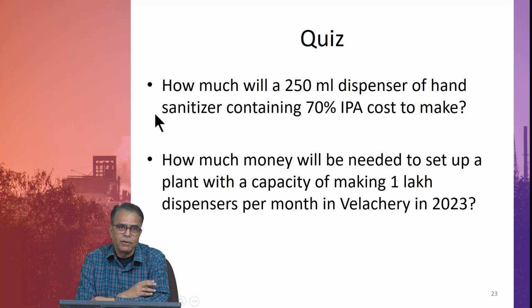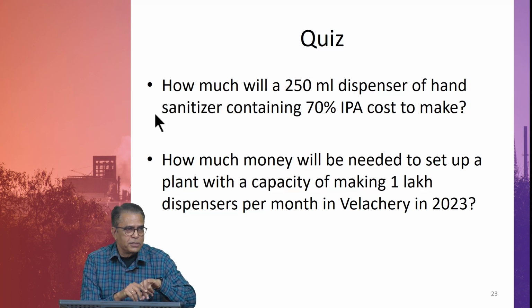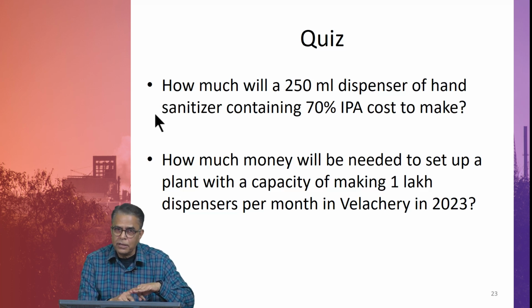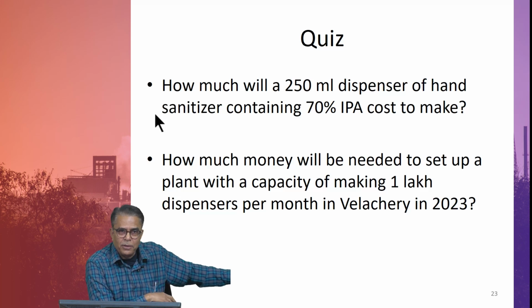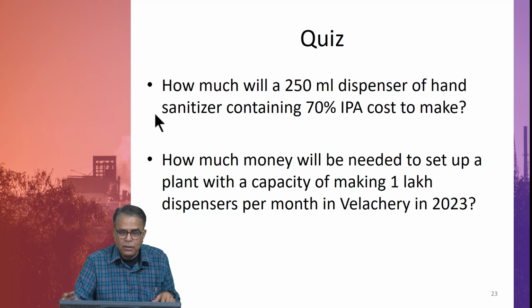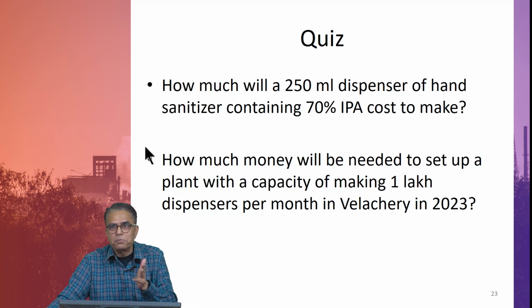That is how it is. If you put that, then you have got something to talk about. You have got some flow diagram, hopefully you have got a P and I diagram, because in all these I ignored the valves. I just said one mixing vessel and put one turbine agitator, axial flow, whatever agitator you have to say, the drive whether it is flame proof because IPA is being handled, how the motor will be fed, where the starters will be, where the substation will be, where the power will come, where the lighting will come, the whole lot of things will have to be thought of, and then you will be able to answer question 1 and question 2 reasonably to the extent that you have spent time in detail.